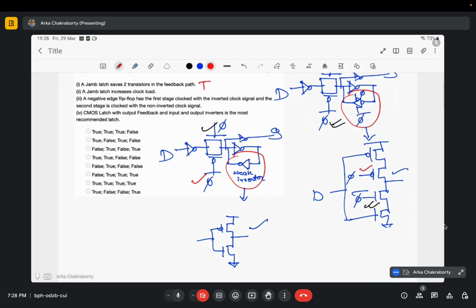So in any signal, when we are giving this signal, we need driver circuitries, and depending upon the load capacitance and resistances it needs to drive, we need to strengthen this driver circuitry appropriately. Okay, so as you have also seen in the delay cases and all. So as to reduce the clock load, we use weak inverters instead of this tri-state mux.